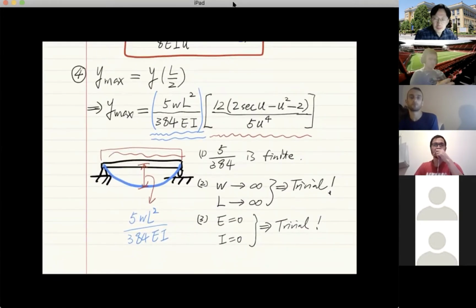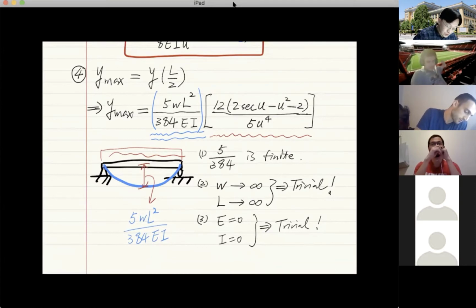We try to express the maximum deflection in this kind of form so we can compare the value of the maximum deflection with axial force versus the one without an axial force. This way you can see the effect of axial force, which is also the effect of buckling, because buckling is caused by the force P. When there's no force P, there's no buckling. So the second term, you can call it the buckling effect. Now, in structural stability, the first coefficient is what we call the linear effect, or the linear order deflection, which is this one here. This is the linear term.